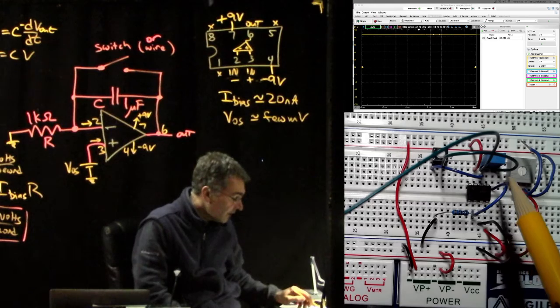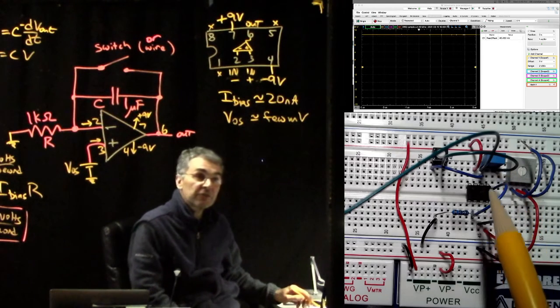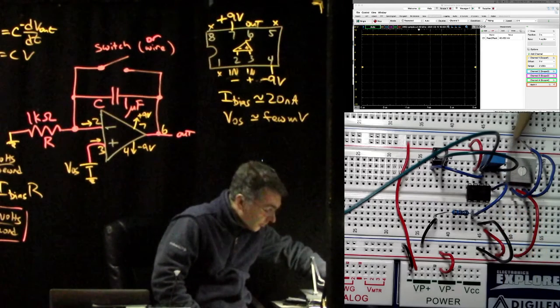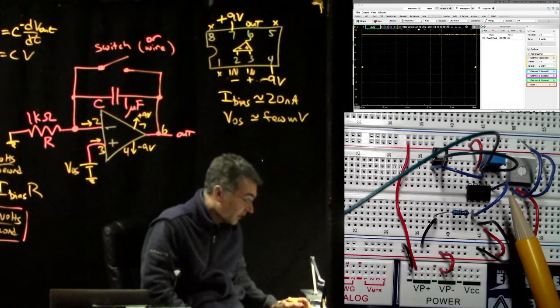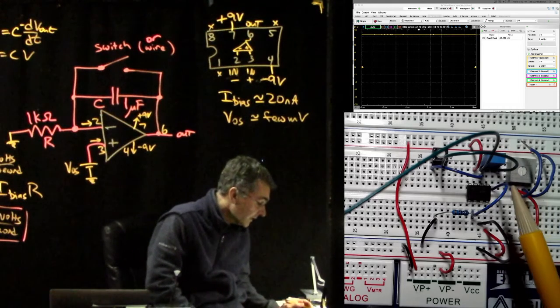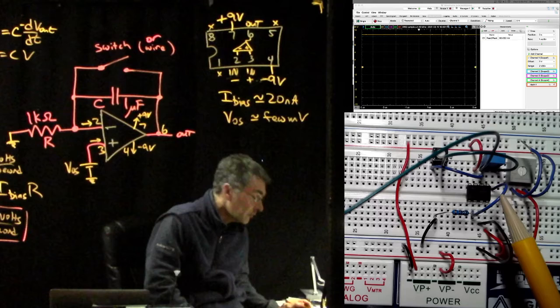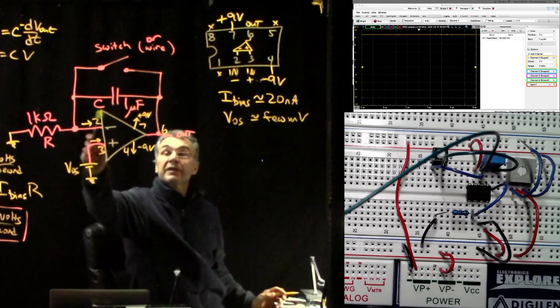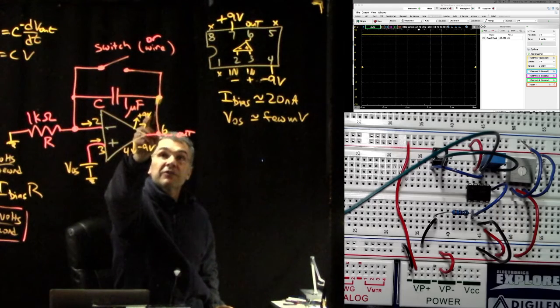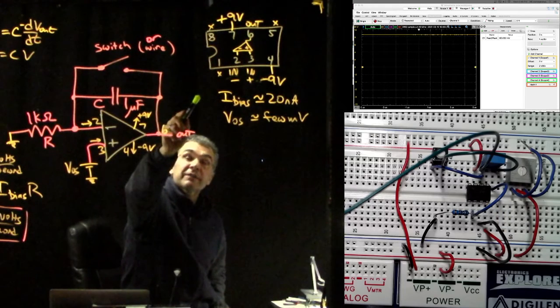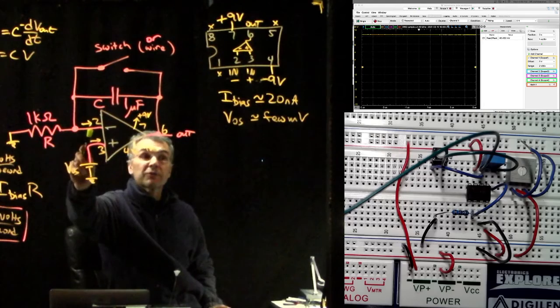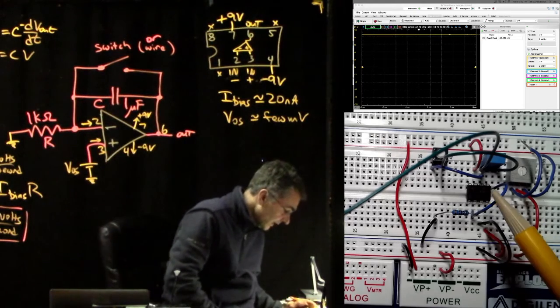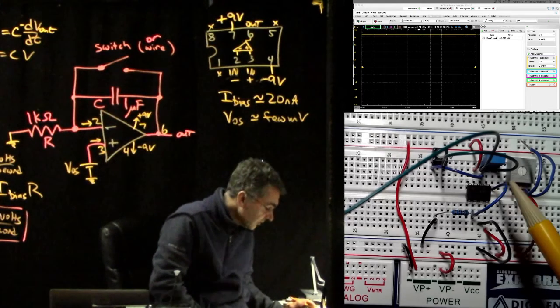Then it was kind of tricky to fit this capacitor in, so the right hand side of this capacitor is actually one row to the right of the right side of the op amp. And then I have this little blue wire going back to pin 2. So basically here's this end of the capacitor, and then the other end of the capacitor is going back through a little wire over to pin 2 here. So that's the inverting input.